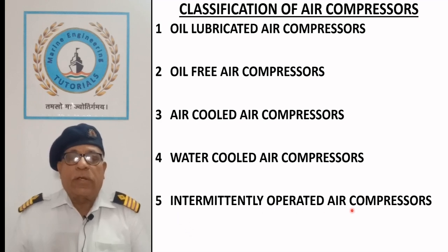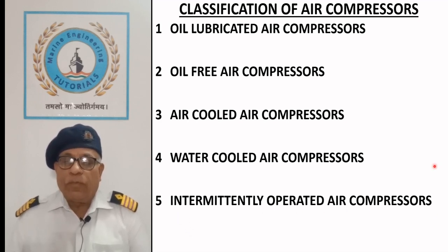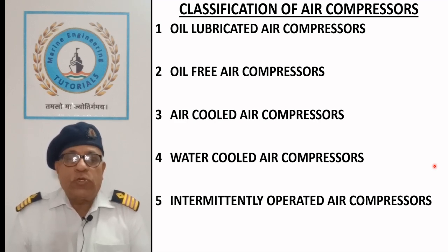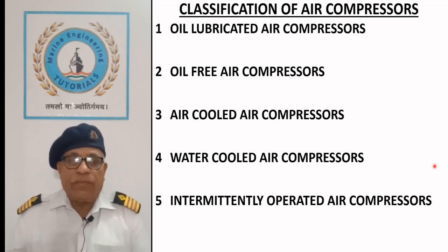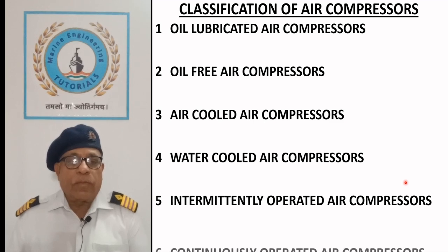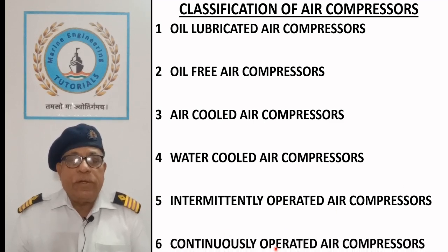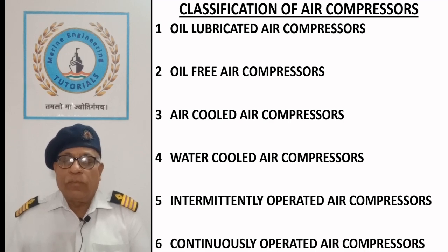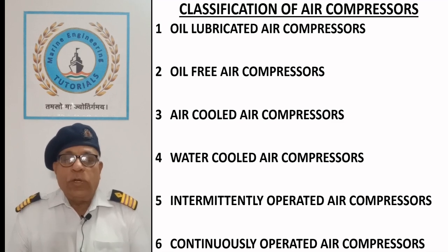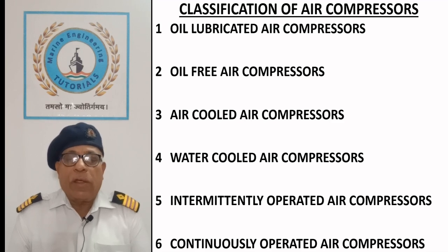Intermittently operated air compressors. Most of the air compressors used on ships for starting air are operated intermittently, thus cooling of the lubricating oil is not considered necessary. Continuously operated air compressors. Deck air compressors usually operate continuously, thus the lubricating oil is cooled by air.